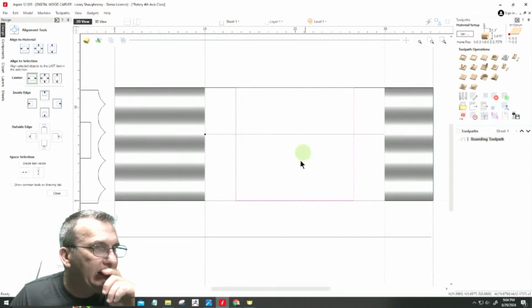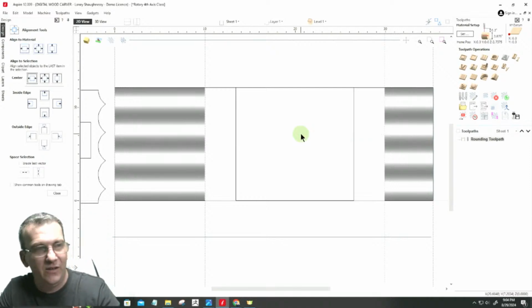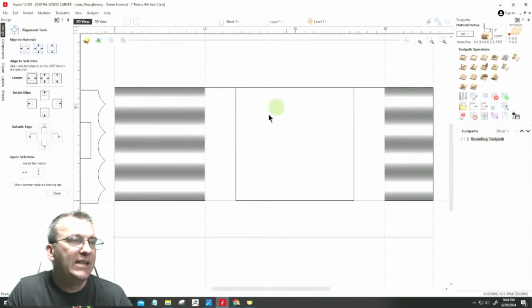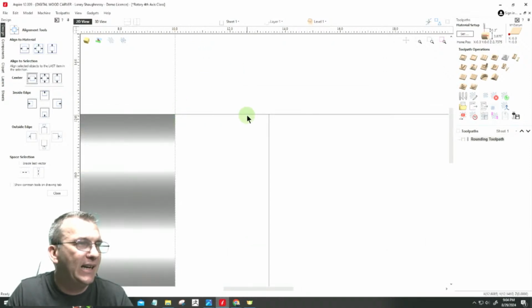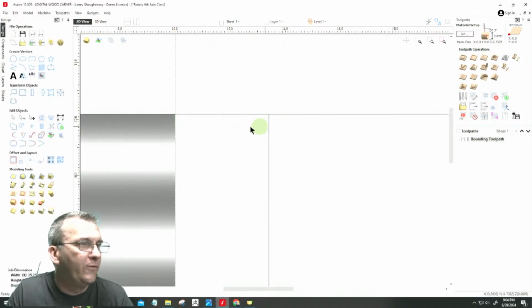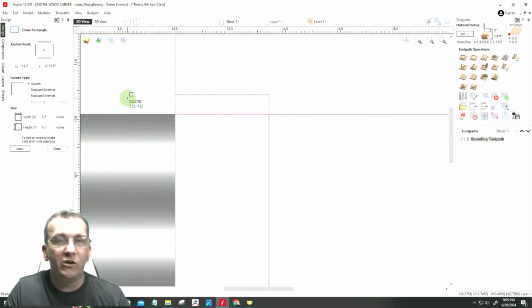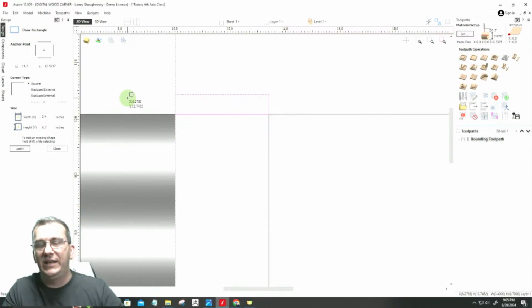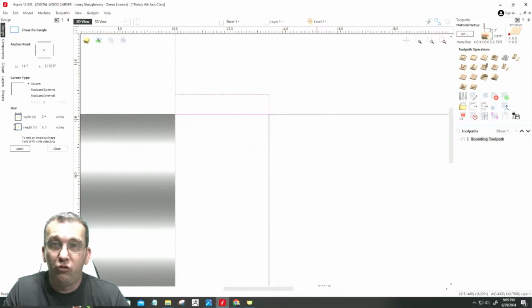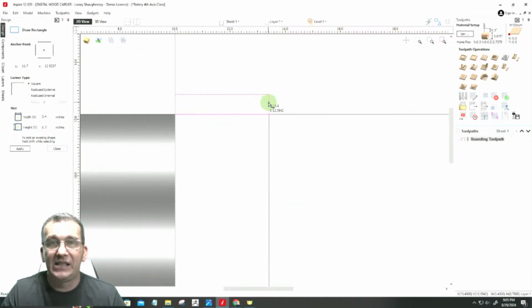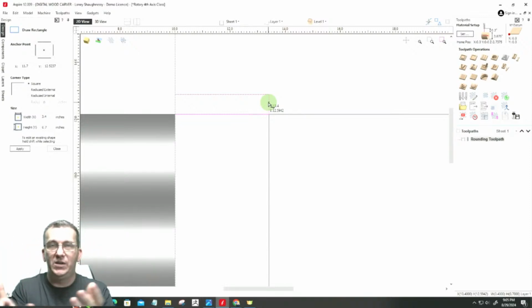The line served its purpose. I'm going to get it out of there. Don't need it. Now, this boundary here is where we're going to do the weave in just a moment. The weave is going to happen right there. But in the meantime, I need to create the profile that's going to happen here. Now, when you're drawing a profile out for your part, when you're creating a profile to do a 2-rail sweep or anything like that, if you're modeling parts in a wrap job, the size of your profile is the radius of your finished part, right?